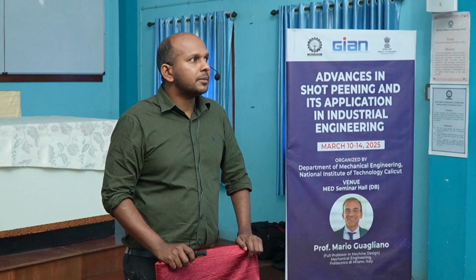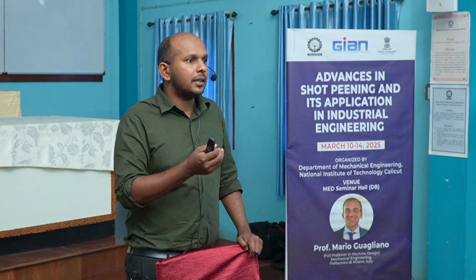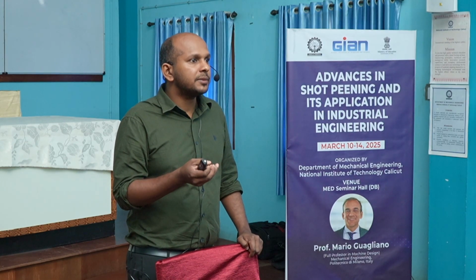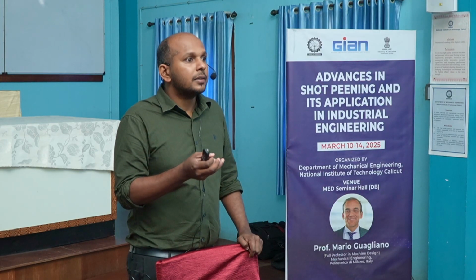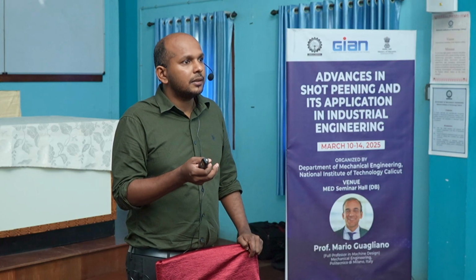But all these things you're suggesting can matter if we are going for conversion coating, right? It might actually create problems if we go for deposition coating. The third study I have included is plasma spray coating, which is a deposition coating only. But don't you think adhesion might be a big problem there? Plasma spray, of course, gives maximum adhesion. Actually, if there is some porosity and cracks, because of this hard particle hitting, we can close this porosity, and then it will be beneficial for our coating.